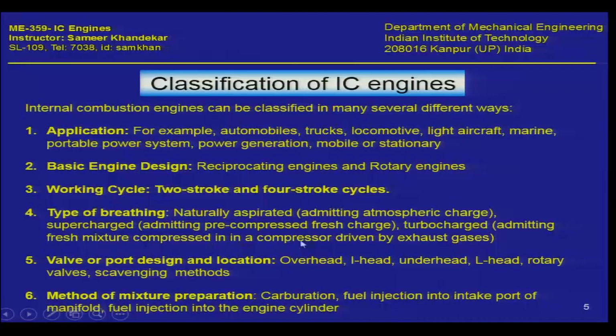Therefore typically you have seen supercharged engines or turbocharged engines. The difference between these two is that a supercharged engine admits pre-compressed fresh charge, which is already compressed by some other compressor, by doing some additional work of course, but then you get more work because you have denser air and you can burn more fuel. So these are supercharged engines.